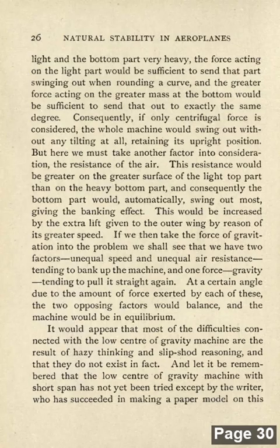But we must take another factor into consideration, the resistance of the air. This resistance would be greater on the greater surface of the light top part than on the heavy bottom part, and consequently the bottom part would automatically swing out most, giving the banking effect. This would be increased by the extra lift given to the outer wing by reason of its greater speed. If we then take the force of gravitation into the problem, we shall see that we have factors, unequal speed and unequal air resistance, tending to bank up the machine, and one force, gravity, tending to pull it straight again.